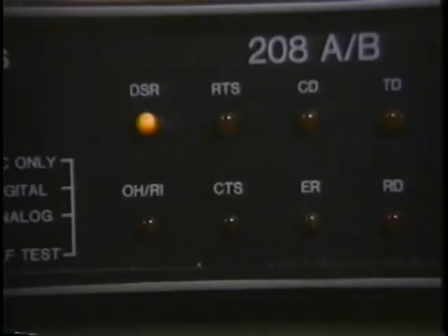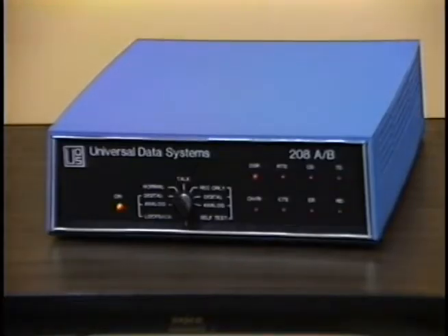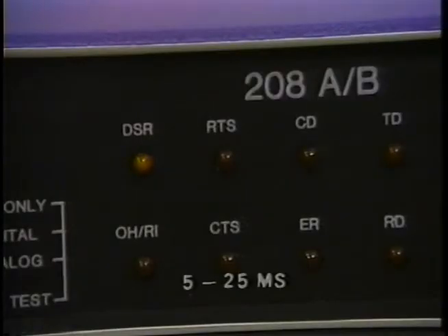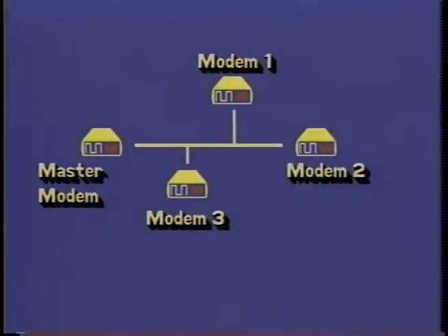The request to send, clear to send delay is usually the longest for dial-up use with 202, 201, and 208 modems. 150 milliseconds, about 1/6 of a second, is typical for dial-up. The delays are shorter for the multipoint private line applications. Generally, the faster the modem speed, the longer the request to send, clear to send delay. The central site receiving modem requires time to tune itself to the incoming signal before receiving data. High-speed modems with very short request to send, clear to send delays are called fast poll or fast train modems.